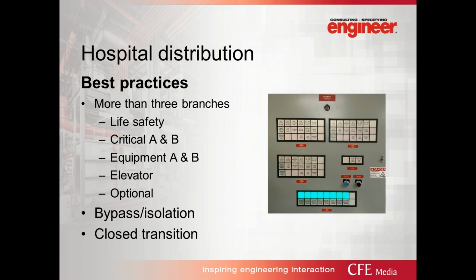Many elevators these days use regenerative power, so best practices dictate isolating this equipment from other sensitive loads. So you may want to give elevators their own transfer switch. And as discussed earlier, things like cooling systems may warrant their own subdivided branch as an optional branch.